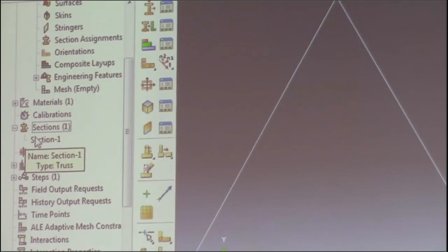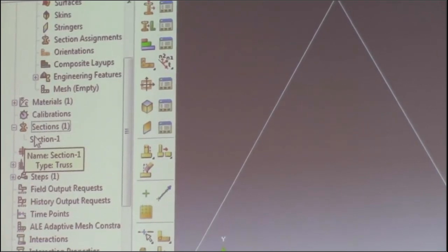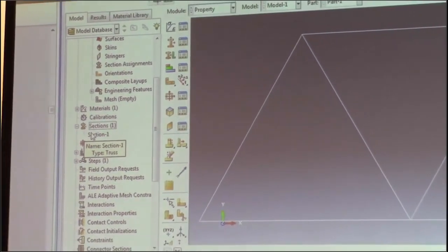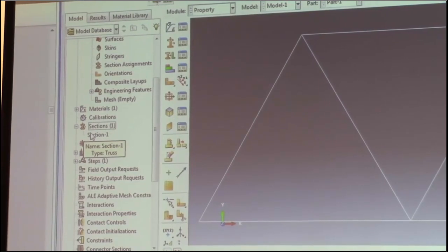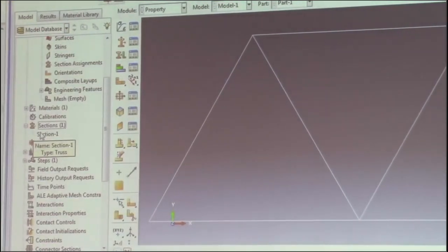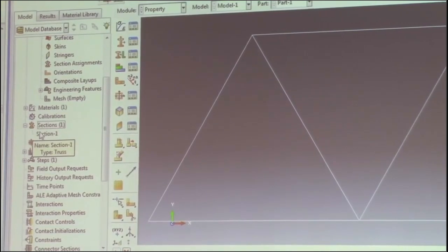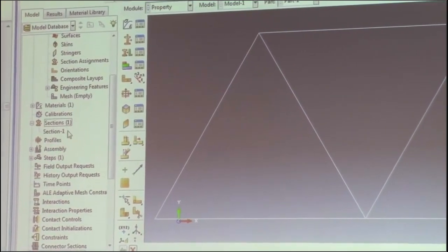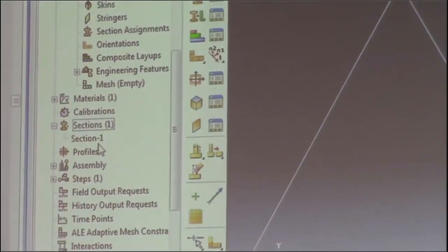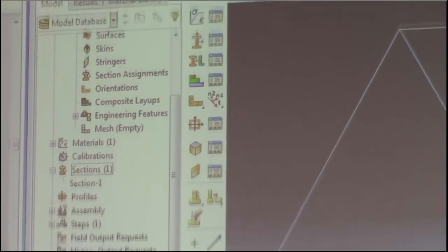So if we want to know the stress result or displacement result or anything related to the truss problem, we only care about the cross-section area. But later, in my third tutorial, when we talk about the beam problem, we need to know the cross-section geometry, either circular or box or any other shape. We need to know the exact geometry and the detailed size of each, because at that time we need the moment of inertia, and to use it, we need to know the geometry. But for our problem today, cross-section area is good enough.